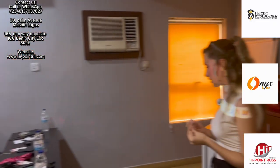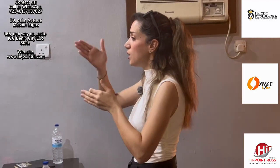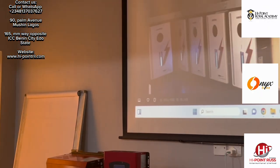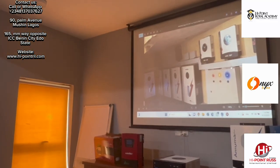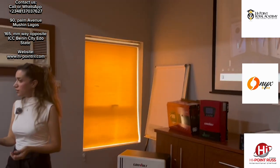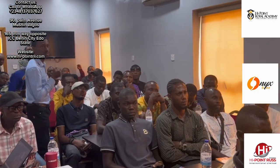Okay, you are close, but the real answer is that when this charging current is a high amount, it's easy for you to have a bigger backup storage. You will parallel 2 or 3 or 4, because your inverter can already charge these batteries at the same time. Because the tubular, how many amps do we charge it in general? 20 to 30 amps.